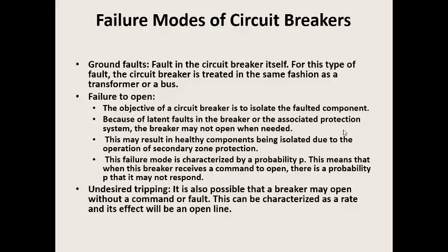How about the failure modes of the circuit breakers? See, the circuit breakers can have either what we call a ground fault, and in this sense, this behaves just like any other component, like a transmission or a transformer. But there are two other failure modes which can have a very serious effect on the reliability of the composite system. One is the failure to open.